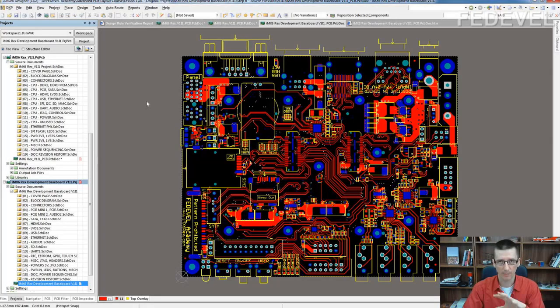The baseboard is kind of a cheap PCB, and this kind of PCB will be manufactured by a company which doesn't have very advanced PCB manufacturing technology. So you need to always ask them or check with them what are the limits, what are the minimum values which you can use on your PCB. Or you can find it on their website.